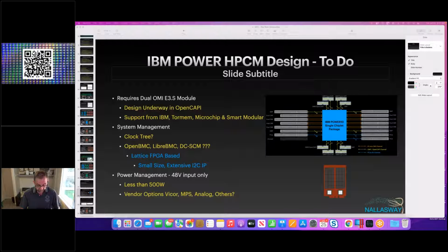So there are a lot of security problems using a BMC that is off-the-shelf hardware. You can't see what's inside that ASPEED. You don't know what that root of trust is really doing. And in this new era of security, you really need to be able to see what your hardware is doing as well as your software. And then this plays into the root of trust. There is a root of trust on those ASPEED BMCs, but we would either pull that into an FPGA or put a separate root of trust on there. So that's another offshoot here that needs to be considered. And we need a good, open root of trust solution.